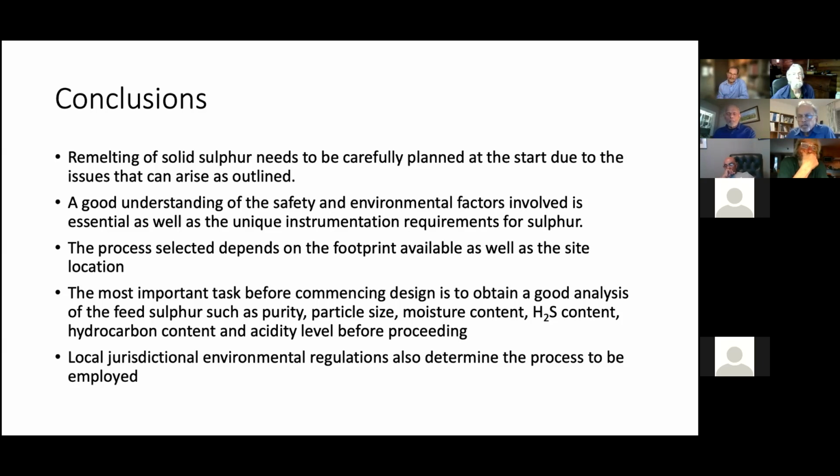Well, my comment really was just looking at the contraction as it changes phase, because at Turner Valley, a company was pumping liquid sulfur rather than move it by truck. They put it in a pipeline, and of course they had the heat wrap. They had electrical heating coils around it, which was fine until they had a thunderstorm and it knocked out the electrical power. And they thought they could drain the pipeline before power could be resumed, but they weren't successful. And the liquid solidified, and like water, it expands. No, which was your point. Well, it bulged the pipe.